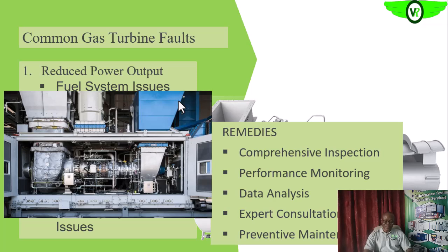Remember that what informed the PM is the fact that some of these components would have gone into the wear stage in their life, from expectations. At those times, it is recommended to do a change out or carry out some remedial action to reverse the trend. Are we getting it? That is what informed the recommendation from the manufacturer. The idea is that before those components go into the wear out stage and eventually fail, we should change them out. So we do not want to play with the preventive maintenance. But of course, from experience within our facility, if it is something we need to change or adjust, we will make the necessary adjustments to fit our particular operations.